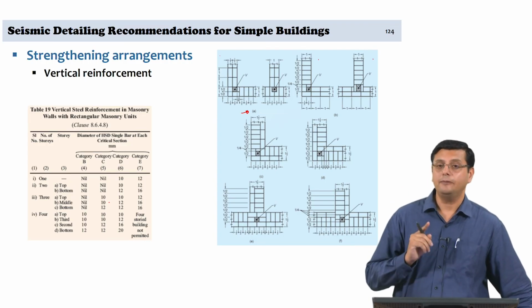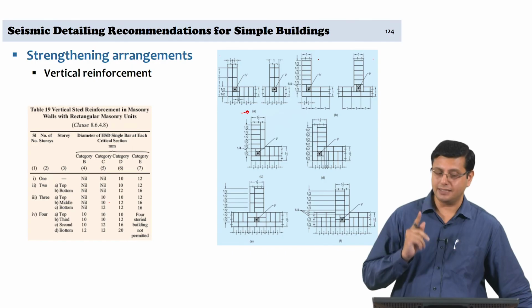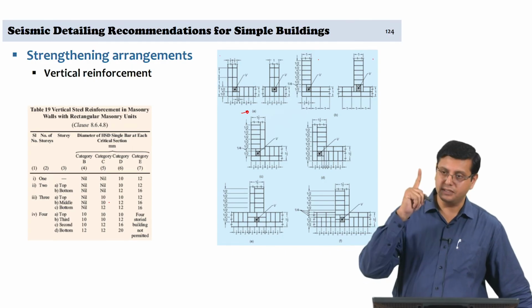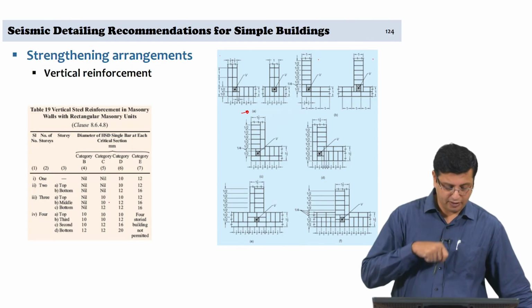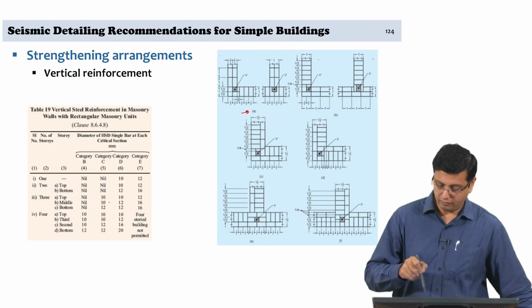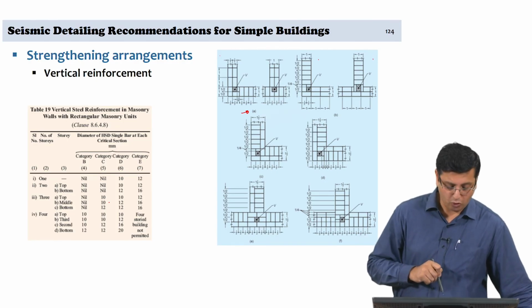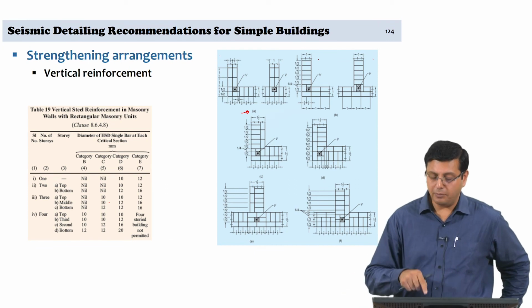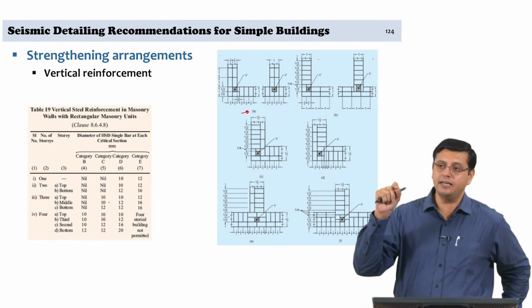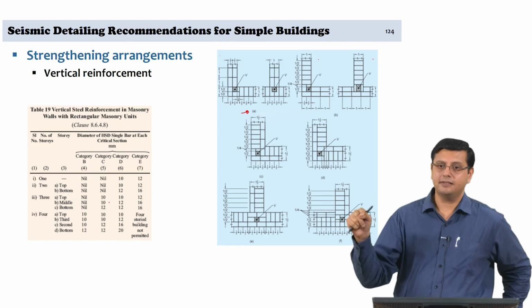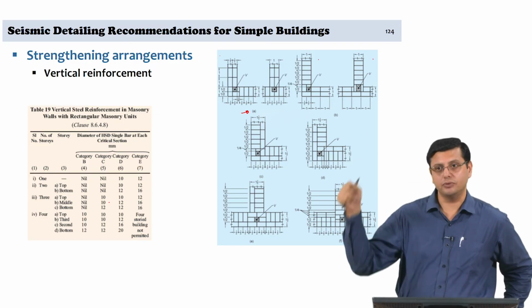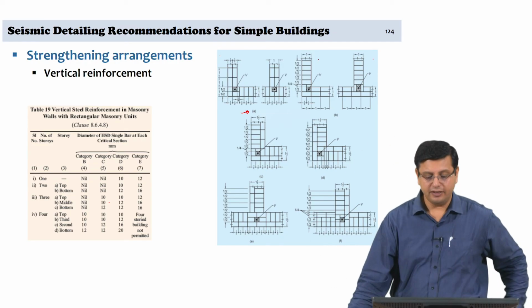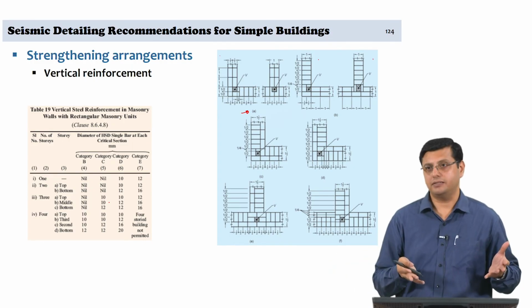Again, it is not a reinforced concrete moment resisting column, it is a tie column. For these tie columns, the prescription is 1 bar, and you have to grout the void, and the vertical bars are connected to the steel in the horizontal bands, and therefore you have continuity between all the steel reinforcement. These are really confining the masonry structure.